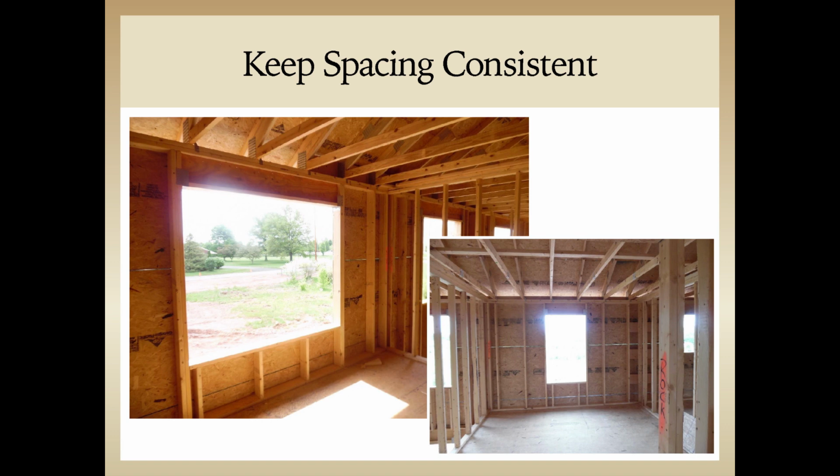If you have, for an example, a 32-inch bay, instead of framing two 16-inch bays, frame one 24-inch bay and one 8-inch bay. This allows your insulation installer to buy only 24-inch wide insulation and cut one piece instead of two. And while this may seem like a small detail, it can have a big impact in material optimization.